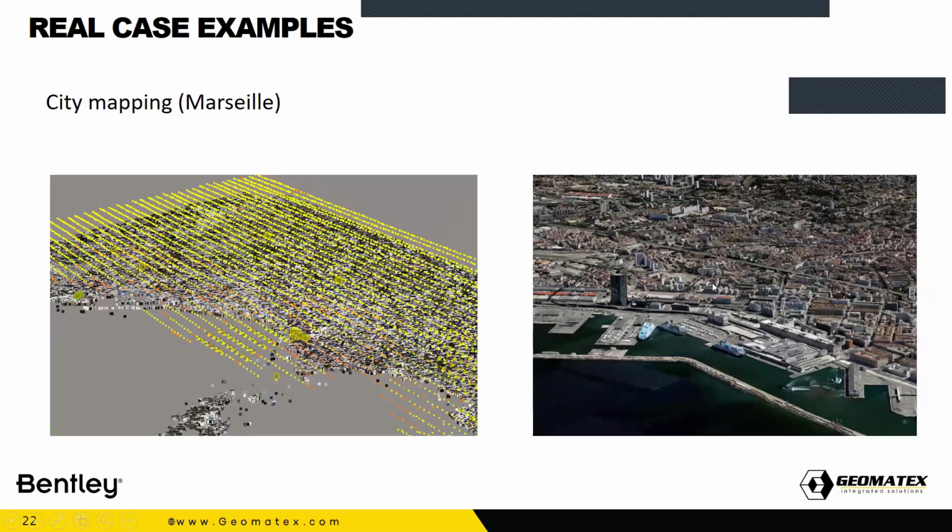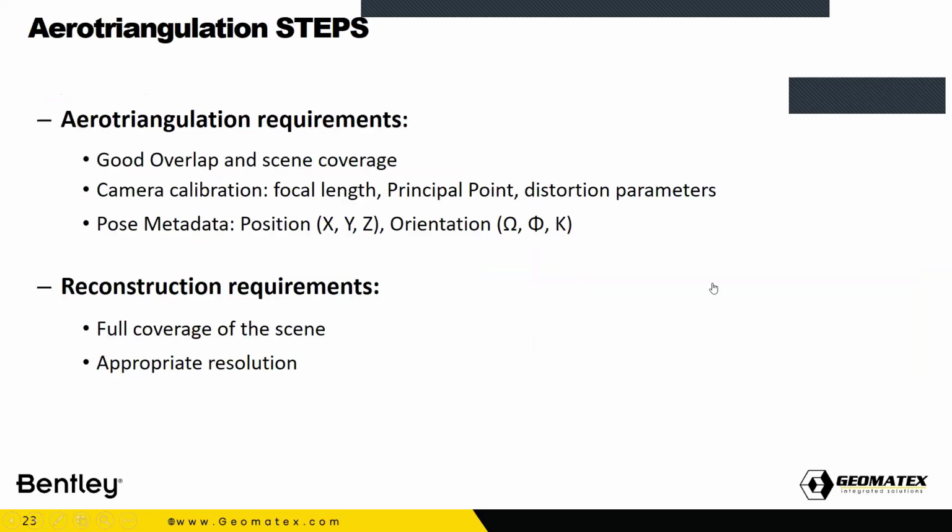And here, if you are doing city scale mapping, it's much more preferable to use those merged nadir and oblique cameras. Personally, I've been waiting for them for maybe more than 3 years to be available on UAVs, because this will impact the industry of city modeling heavily. To cover large areas, you will not have the option to fly twice or 3 times or maybe 5 times to get nadir and 4 oblique data sets. But if you can get it once, it will be very, very good.